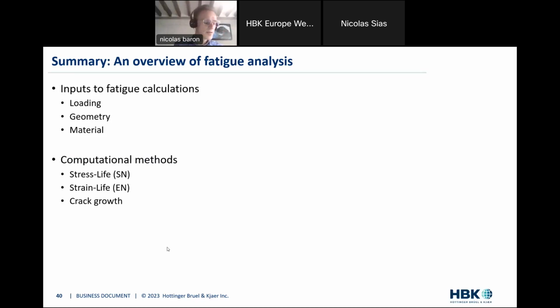The loading part tends to be something that people just overlook, just assuming some random loading or some loading that comes from standards, from regulations. That might be good if you don't have any data at hand. So in the first phases or the first iterations of your design, that might be good. But as soon as your design matures and is about to reach production, make sure you've designed and validated your design with loading that really represents the real loading conditions your end users might impose on your design. That's often called mission profile, if you've heard that name before.